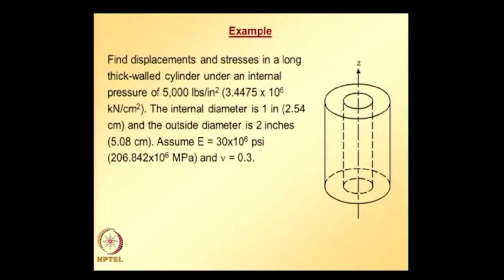Material properties are constant, so they also satisfy axisymmetric conditions. That is, the structure geometry, material properties, and loading are all symmetric with respect to the axis of revolution.